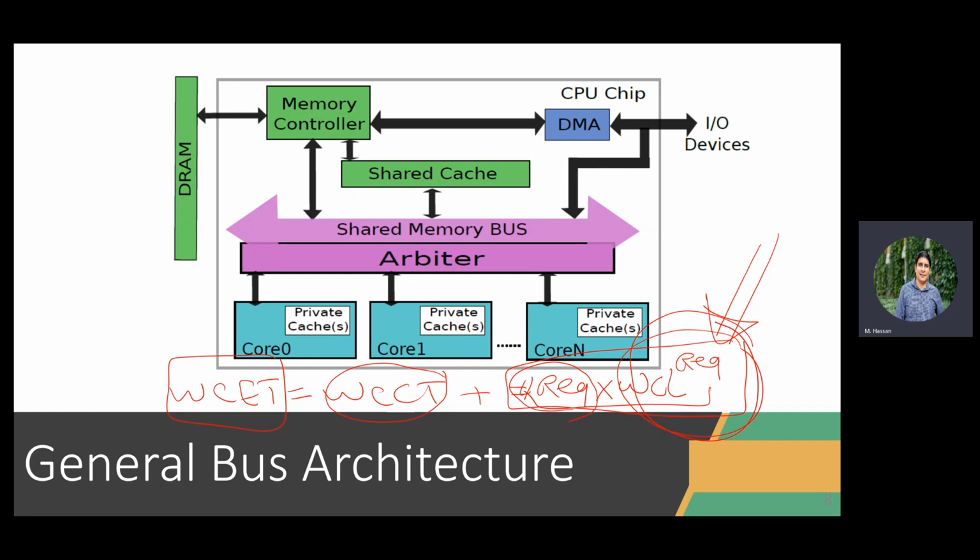For example, in most laptops or most average case high performance architectures, I have what we call a fixed priority, first ready, first come, first serve arbitration, which means I do a lot of reordering. In other words, one request can come to the bus in our laptop and wait for hundreds of cycles without being serviced. Why is that the case? Because it might be a lower priority. It might be because it's not ready right now, so it has to wait a lot more, right?